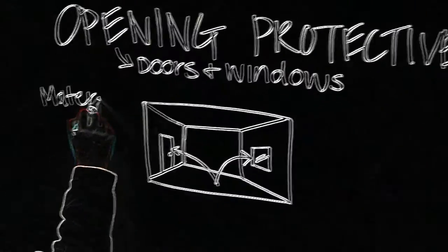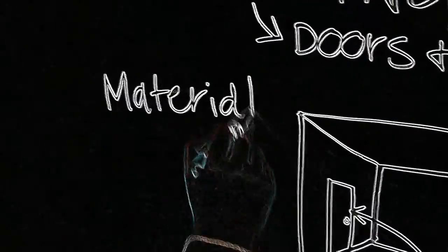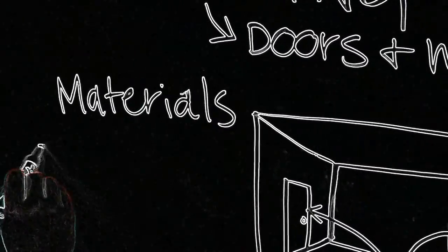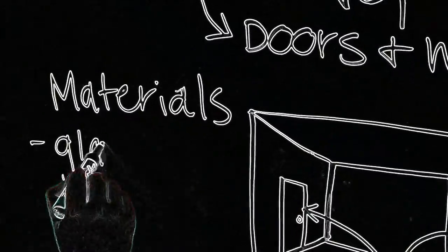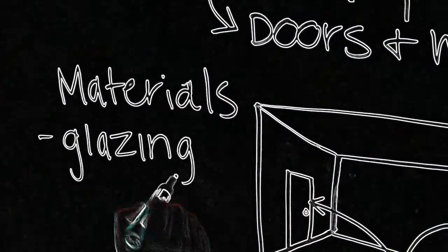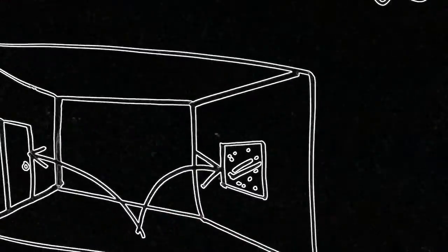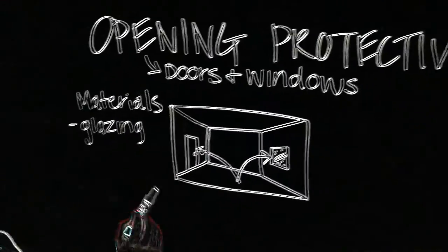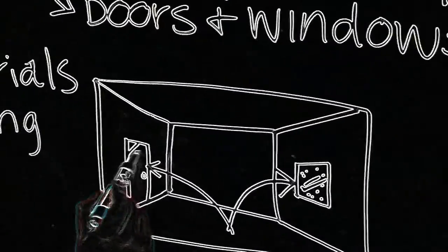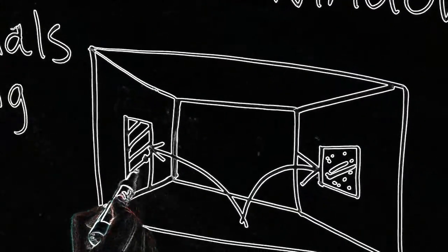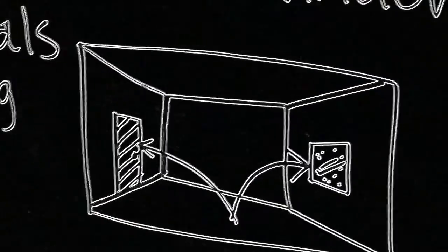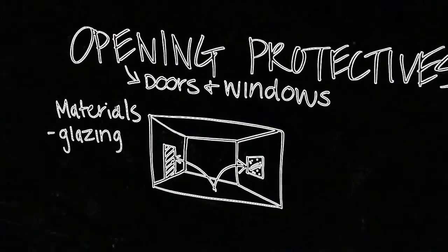Not only are the ratings important to the integrity of the entire wall during a fire to stop the spread of fire and smoke, but they are also crucial for the evacuation of the occupants during a fire. A fire partition usually has a rating of at least 1 hour, but as you can see, if a window has glazing, it becomes a 2-hour rating.